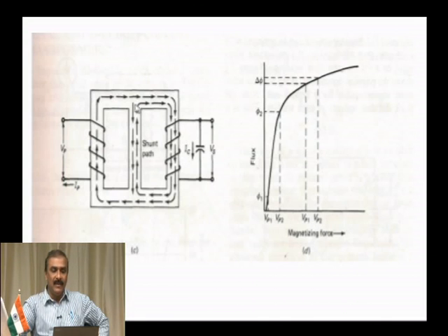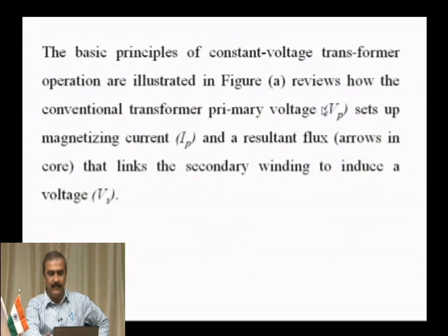So, that is why you provide a shunt path, a resonant path. Of course, a capacitor is connected here for the resonance. You know what is resonance? Connecting an inductor with a capacitor causes resonance. So, if you bring it to resonance, it will go to saturation like this. This is the point where we bank upon the CVTs.